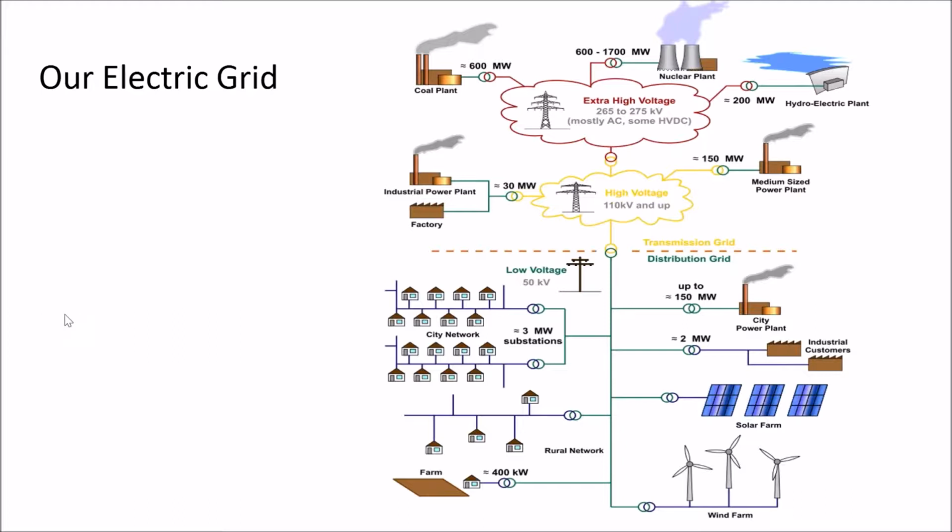but there are ways to start looking at load leveling and building leveling, even some architecturally pleasing ways, like you might have a water fountain on your property that only turns on when you would otherwise be exporting power onto the grid. Or you might put an immersion water heater inside your electric tank so that your water heater does most of its heavy lifting when you would otherwise be exporting onto the grid. All of that stuff is more the purview of battery-based solar design.